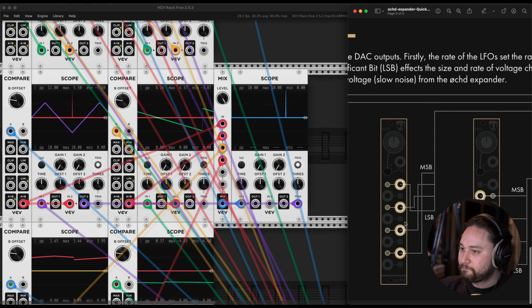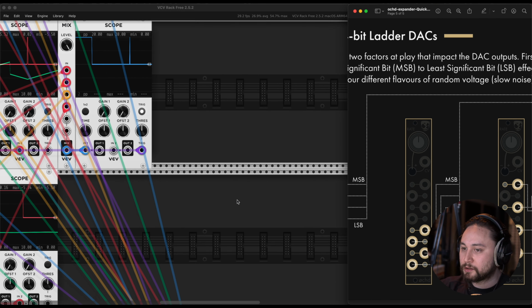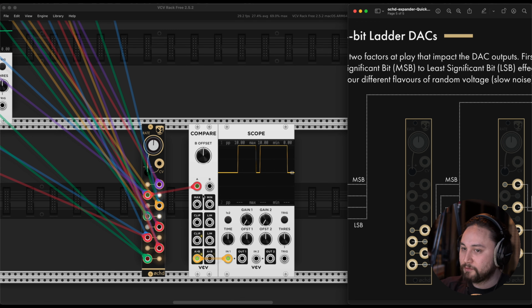This is breaking the rules slightly. It means that our square waves in relation to the triangle waves are going to be phase shifted by 90 degrees, I think it would end up being. So anytime the triangle's over 0, it's high. So it just means that our result is going to be slightly out of phase versus the original LFOs, but I don't think we'll notice. I think we'll get away with this.